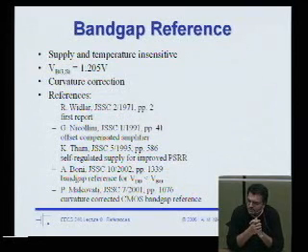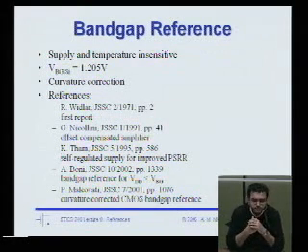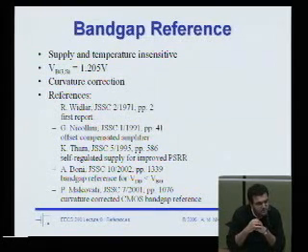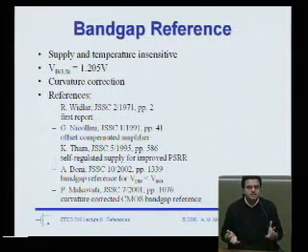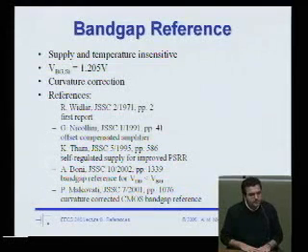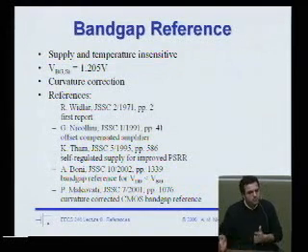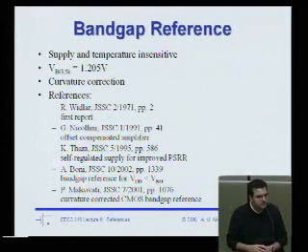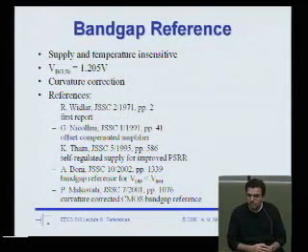Well, in some ways, a bandgap is very much a logical thing, right? I think maybe it was Widlar who designed the first bandgap, but the idea was, you know, this PTAT current has positive temperature dependence, and if I could find something that had a negative temperature dependence, then I could somehow sum them up and get a zero temperature dependence, right? And in fact, if you're a good bipolar designer, you knew very well that the VBE has a negative temperature dependence, right? That's why we get the current runaway problem in bipolar transistors.